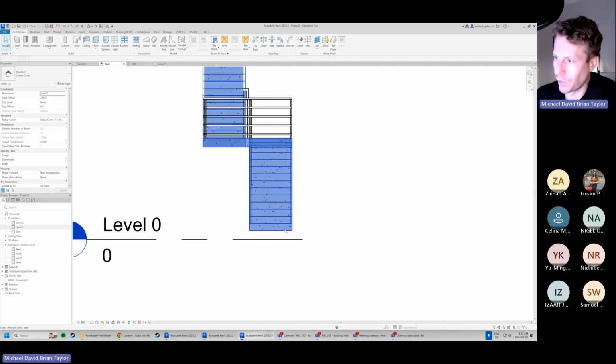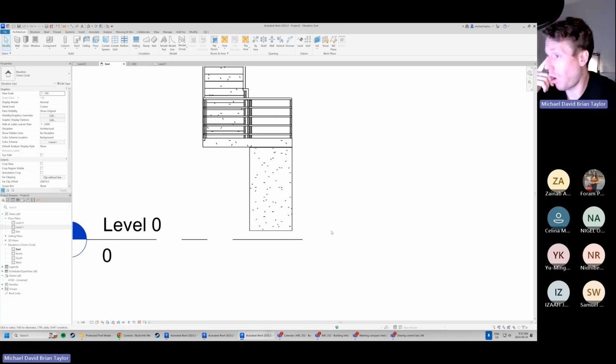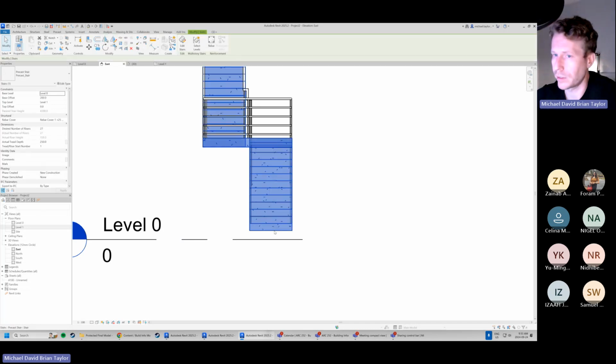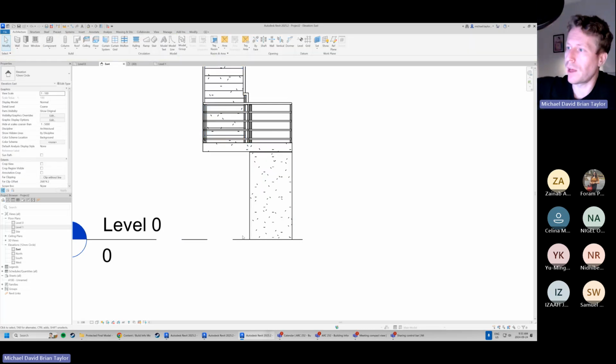It happened so quickly. That stair has now all very quickly been updated to reflect that very small change, but if you were drawing this by hand or in Revit, that's a lot of extra drawing to do. So we've done it with literally just giving some instruction to Revit to say, move the base offset up by 200. I'm going to undo that, just so you can see the power here. So let's make that 0 again. We should see that jump down. So all of that math quickly done in no time, right?